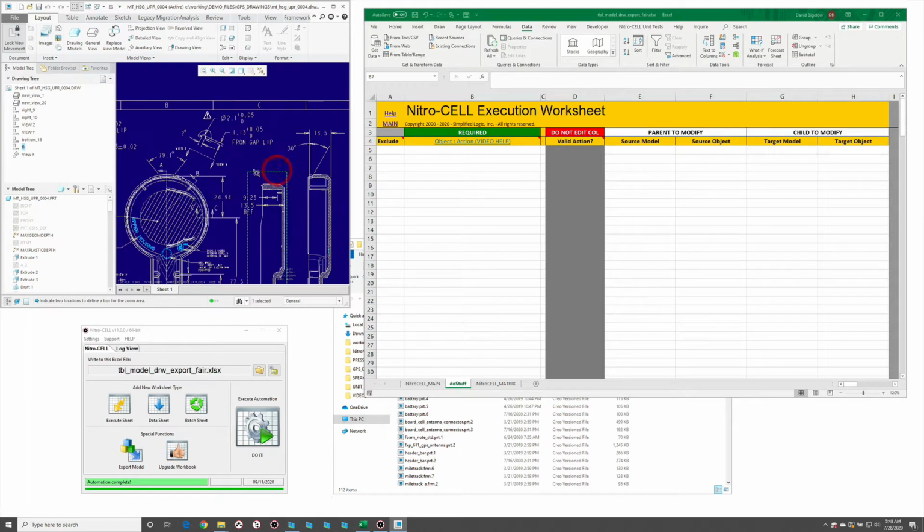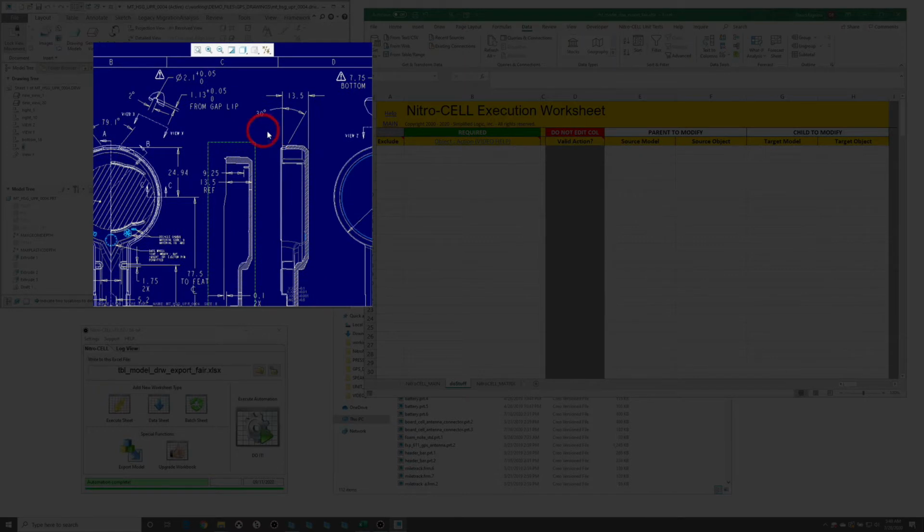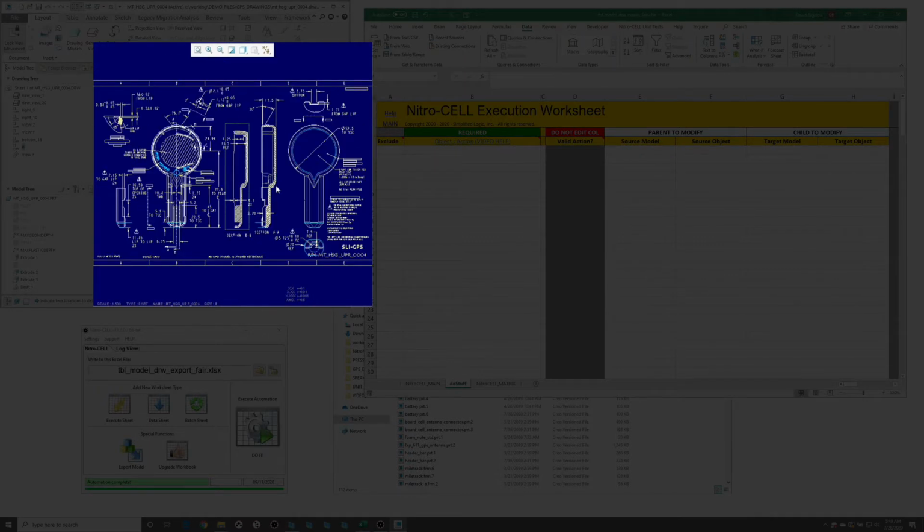Okay, first article inspection reports are typically reports generated for inspection and quality purposes. How they typically are done is whenever there's a prototype component made or initial runs for production or sampling, they'll take the print and they'll put symbols or manually annotate a printed drawing and then document each of those items in an Excel document or manually on a grid paper, and then take measurements and classify whether the part is conforming or not. It's really kind of a painful process to go through.